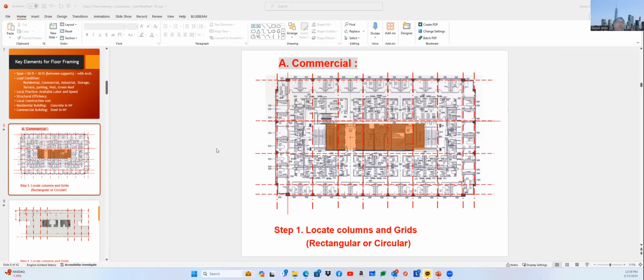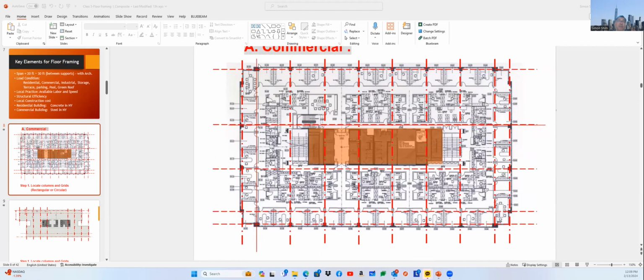All right. Now this is very typical, standardized. One thing that I just said, because this is the building architecture plan, the corner of the slab is offset. So instead of having one corner column, they put two columns, one column on each side. So try to make the corner view an open corner view.